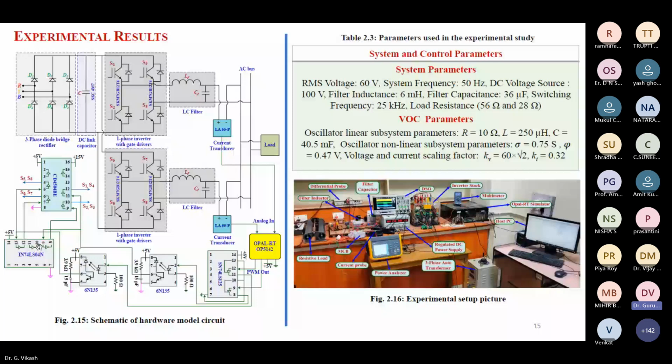Similarly in the case of the level shifter, we have to apply 5 volts across 1 and 8. 8 is the ground. Similarly we have to apply 15 volts across pin 16 and 8. So we have to apply the supply, then only the IC will work. Here 3 is the input, 2 is the output. If we give the 5 volt magnitude pulse at the input pin, the output pin will give the 15 volt pulse. That's it. It simply shifts the level of the control pulse.